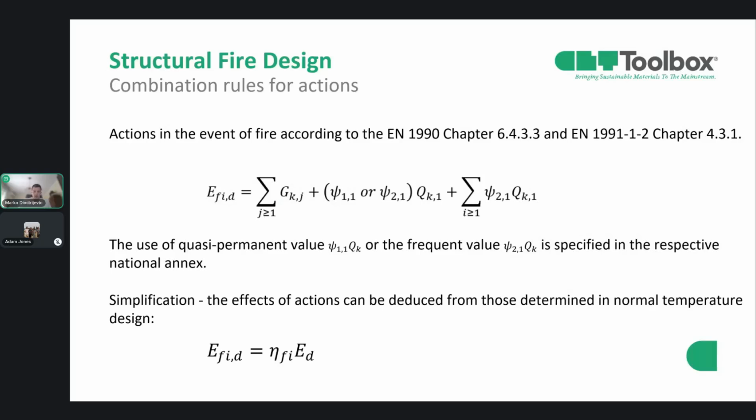The combination factors psi are determined by different load categories of structural elements, and they usually range between 0 and 0.7. The choice of combination factors must consider whether structural elements' maximum load can be expected to occur in fire situations. A simplified method is there to verify the structural load-bearing capacity in fire based on the reduced load.